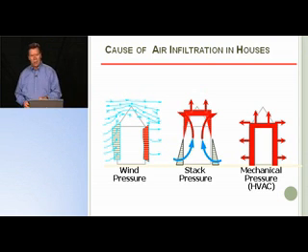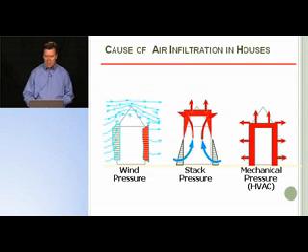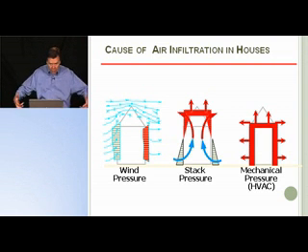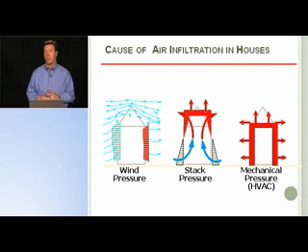Another mechanism for air infiltration or pressure differences in homes is what we call the stack effect. Warm air is more buoyant than cold air, so it tends to rise. Just like if you've ever held your hand in a fireplace, not with the fire operating, you can feel a draft going up the chimney. That's because the warm air in the home is seeking a cooler environment. So that's what we call the stack effect.